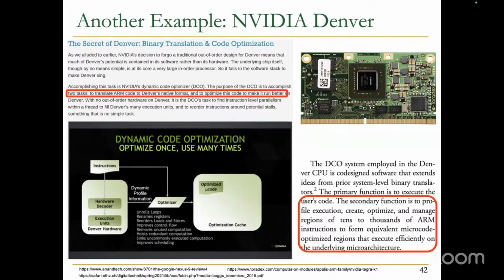You can see that there are instructions, and you go into an optimizer. That optimizer is actually software, and it's using a lot of the concepts that were developed by VLIW processors. Some of them actually have hardware support as well internally.